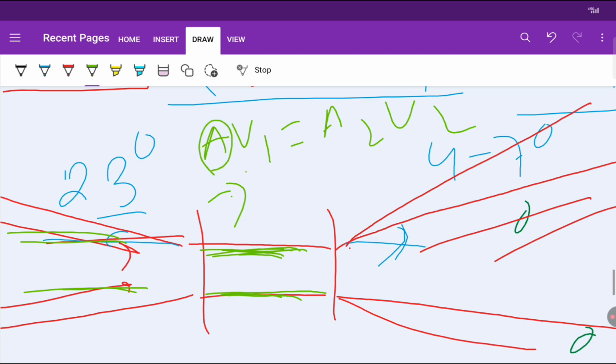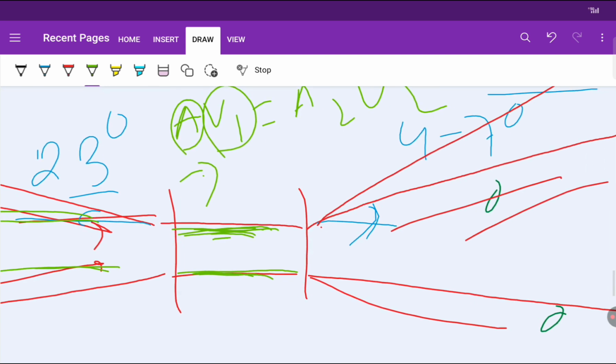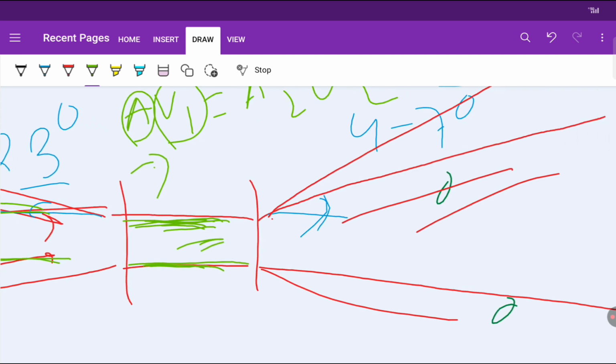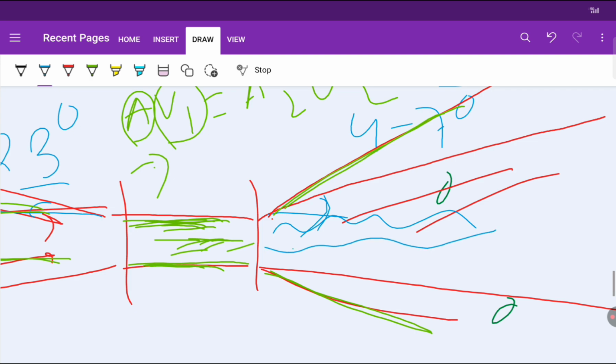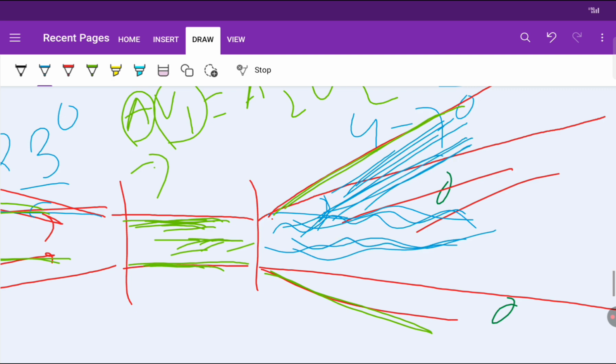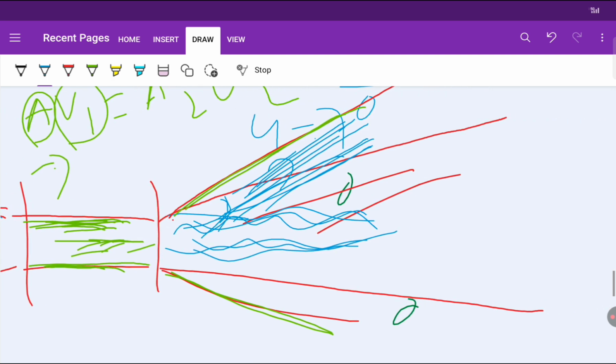So if area is reduced, velocity will be more, right? So in this case velocity will be more. Okay. So if the velocity is more, then what will happen? The water will pass at a higher rate, right? A large chance of flow separation will be there. Okay, water will pass this way, right? It will not pass this side. Okay, so this portion is useless. So it is called flow separation. Okay, so here eddies will be generated.